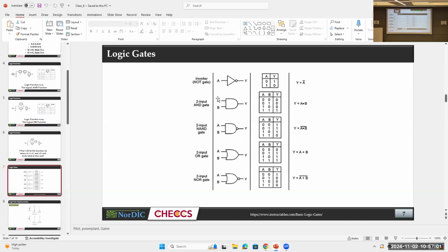So this is the AND gate, and this is the truth table of the AND gate. We have already shown you the truth table. The series connection is simply the AND gate, and if you match the truth table, the switches are treated as inputs here. So this A and B here are x1 and x2. Some people represent inputs as x1, x2, x3, x4, and some people represent them as A, B, C, D. So this is actually a two-input AND gate.